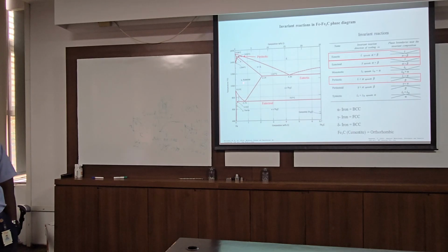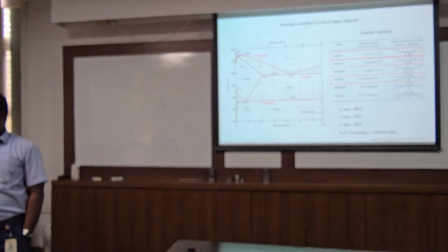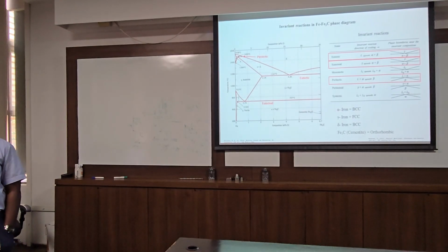You cannot use steel above, I don't think we can use it above 800 degrees. There are different classes of materials based on temperature: low temperature, high temperature. For high temperature you choose nickel based superalloys, which are used in gas turbines, where it will go to 1200 degrees centigrade.